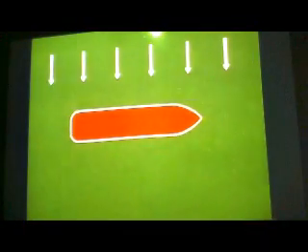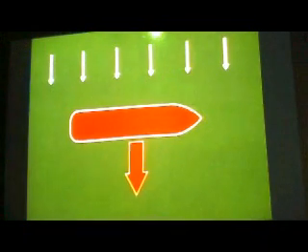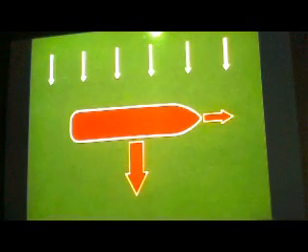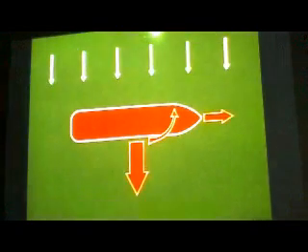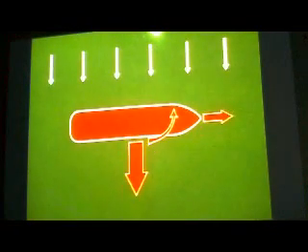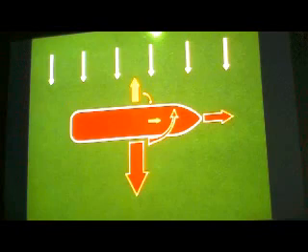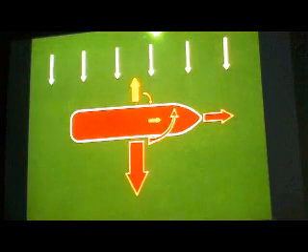If a stationary vessel in still water is subjected to a strong wind, the aerodynamic effect causes a lateral force, a longitudinal force, and a turning moment. Aerodynamic effects are shown in red. As the vessel starts to drift under the action of these forces, the hull's hydrodynamic effects come into play. These are shown in yellow. The steady drift of a vessel is determined by a balance of these forces.